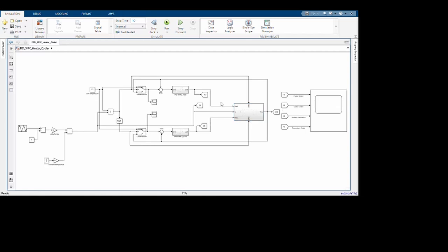So now that we know that, we are observing 4 things here. We can observe 2 other things as well, but this is not very mandatory to observe. The very first thing is the heater control output. Then the second is the cooler control output. The third is the ambient temperature disturbance. How much disturbance are we getting? And the fourth is the actual temperature output.